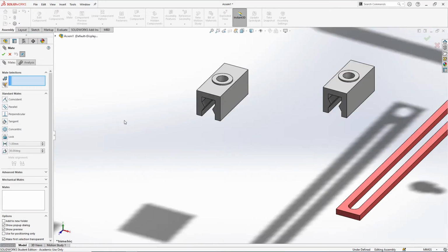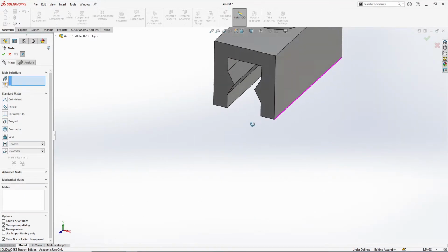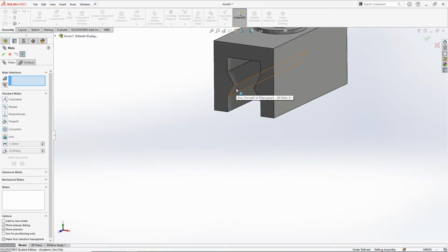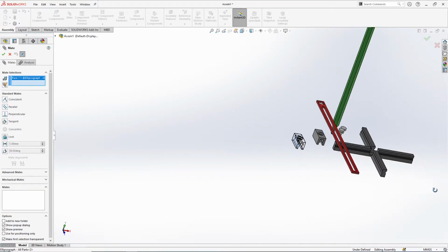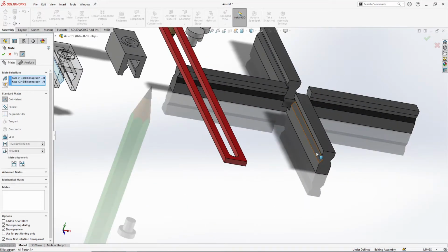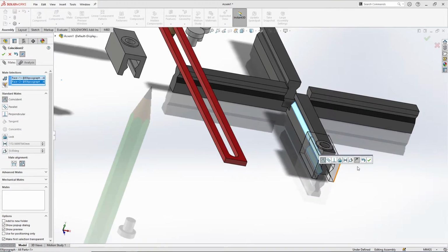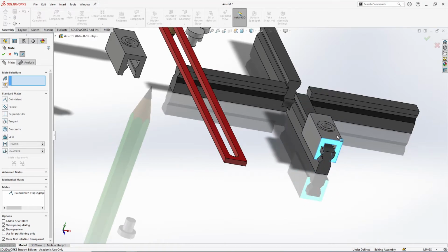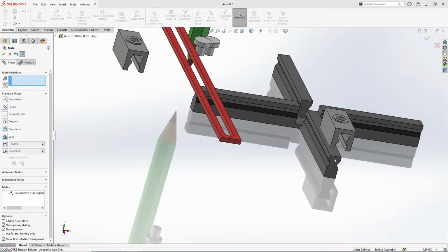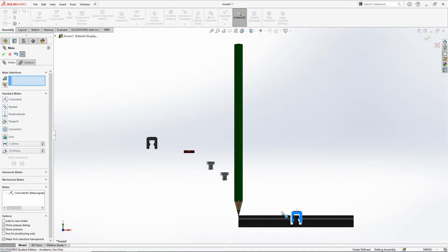So I have to zoom in and turn my models a lot. First I want to say that this side should be aligned with that face of my assembly. I can click on the green check mark right here. Now I can move this part still around in all kinds of directions. Easier to see the effect of mating those 2 faces if I look from the front.